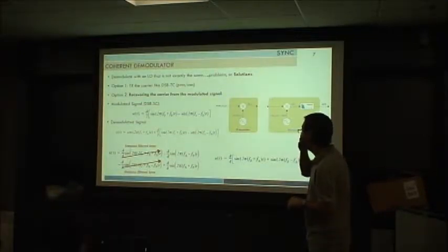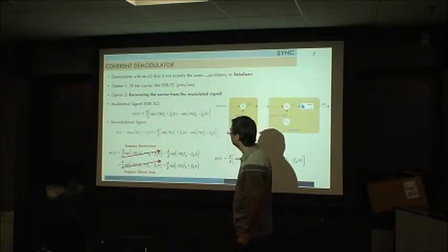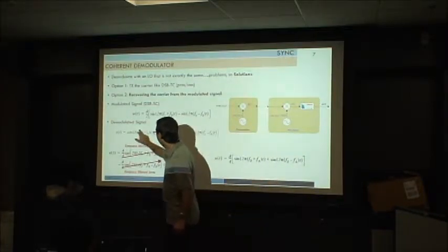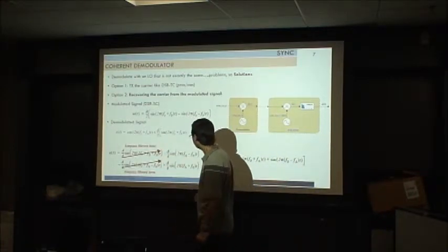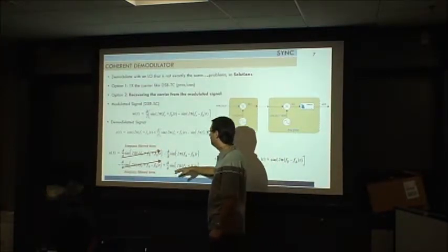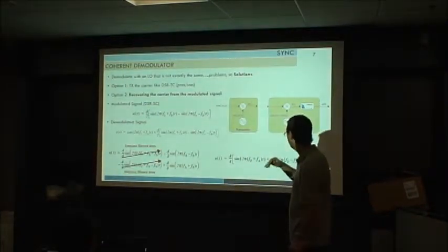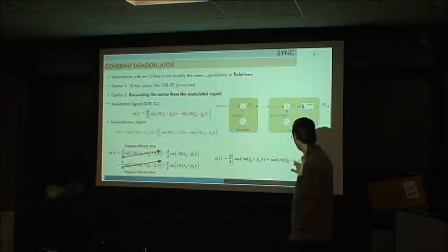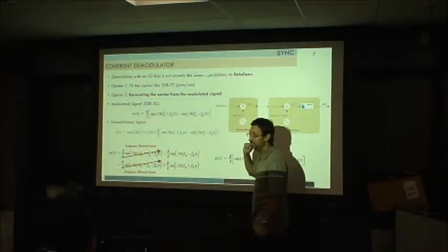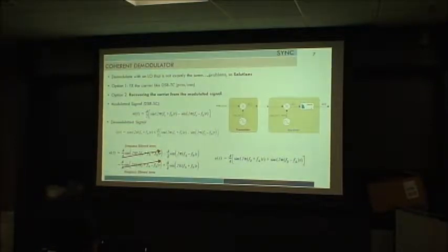Okay, so if this is our transmit signal, and we follow this, we are making the modulation here. If we follow the math, we know that the high frequency terms will be filtered out. Okay, so at the end it will be this one, with this error being the error between this carrier and this carrier. Okay, so that will happen in a real case, not the ideal case.